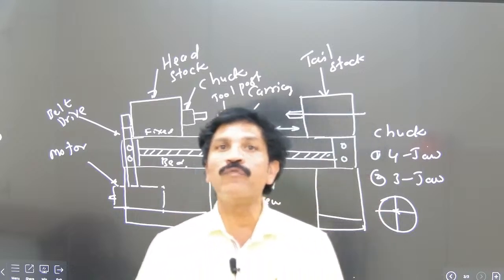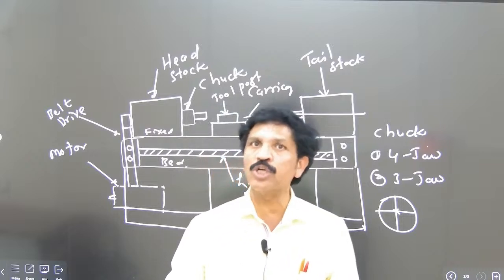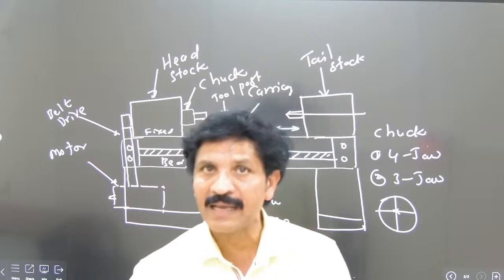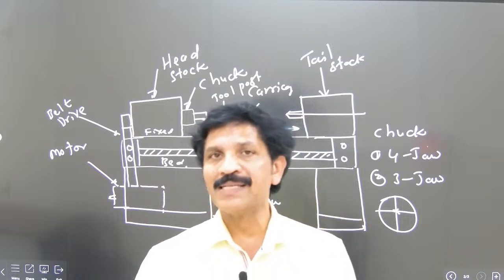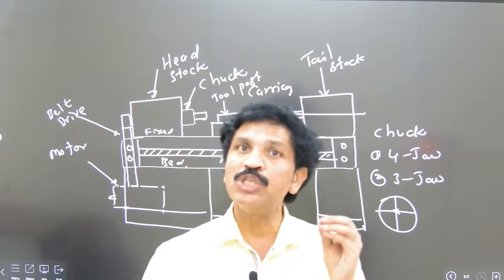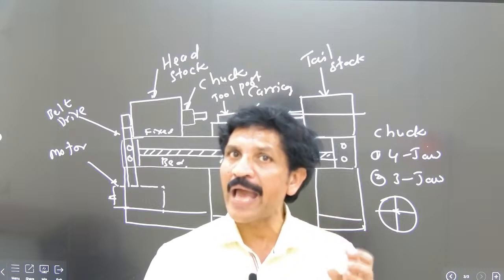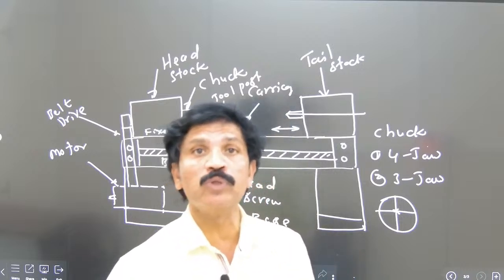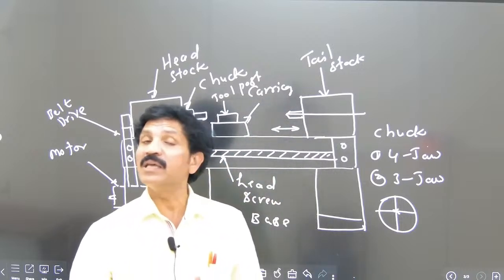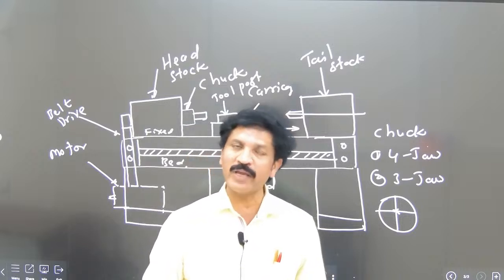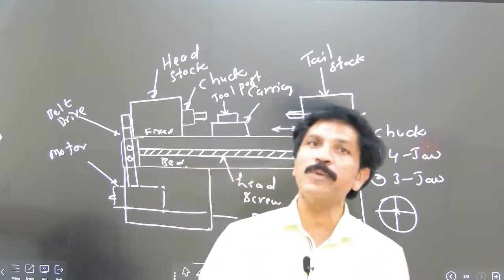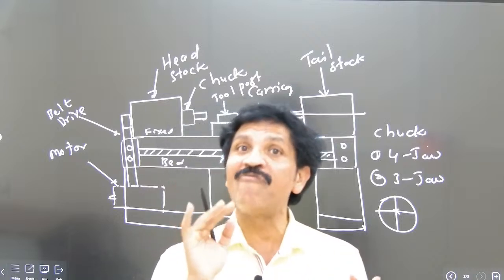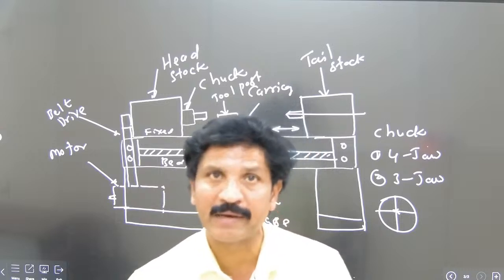Before we operate whatever operation you want on the workpiece, all these steps are necessary. The setting of the tool and the setting of the workpiece, these 2 are a must and should coordinate accurately. Then only is it possible to remove the unwanted material from the workpiece uniformly. That is not a problem here, but the case is the uniformity of its circumference. That is important here.